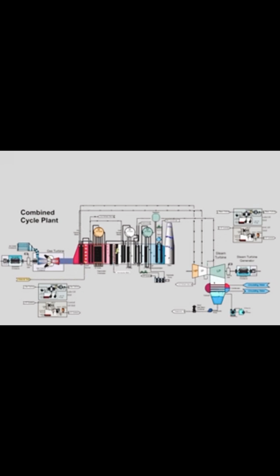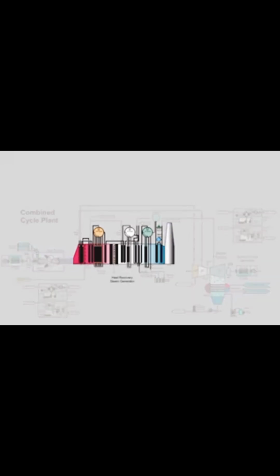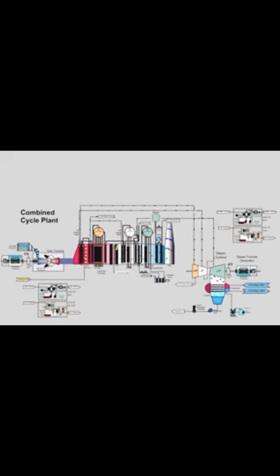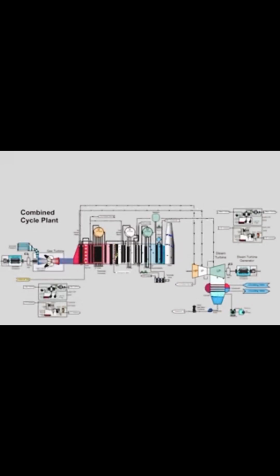In conclusion, a combined cycle plant utilizes a gas turbine to produce electricity in the gas turbine generator. The exhaust is then used to generate steam in the heat recovery steam generator. That steam is then converted to electricity in the steam turbine and steam turbine generator. Numerous support systems are necessary to support the operation of the plant, and major plant equipment such as the turbines and generators. Utilizing a combined cycle plant increases both the amount of electricity generated by the plant